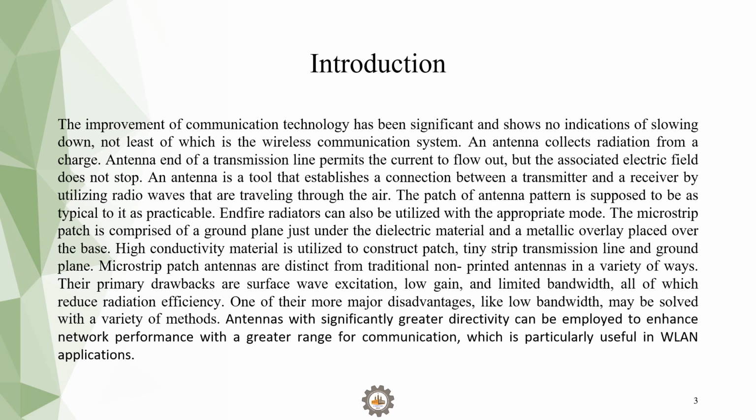The microstrip patch is comprised of a ground plane just under the dielectric material and a metallic overlay placed over the base, and the conductive material is used to design the antenna. Here, the circular microstrip patch antenna is designed in place of the general regular antenna to increase characteristics such as gain, directivity, bandwidth, voltage standing wave ratio, and the return loss.